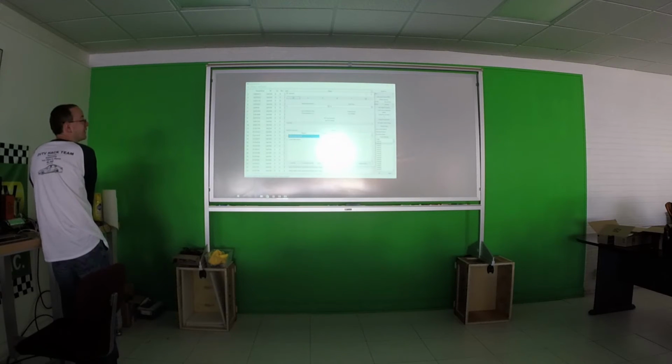In fact, you can see Collin here had to code ID filtering for me. What we did is we would play this back and start deticking these IDs. In Playback, you can detick the ID here on filtering and it will not send those IDs. What we did to figure out the minimum baseline to make the inverter work is start deticking these until the inverter gave up.